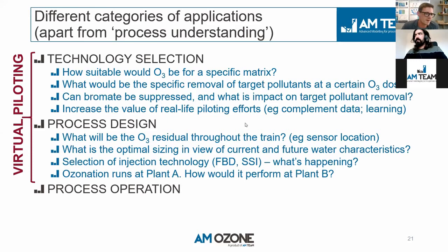And people often confuse such modeling with CFD. They have different purposes. For example, CFD will tell you how should we design a nozzle, or what is the impact of putting a baffle here or there. This model will give you sizing information, conversion information. It allows you to simulate 200 days. So that's a different application. Perfectly possible. I think it's a very good question.